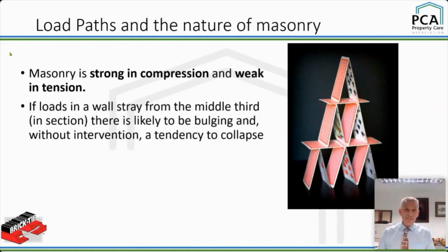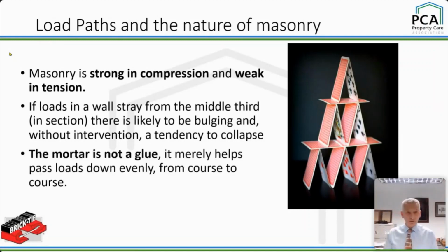That's what we mean. If loads stray from the middle third in section down a wall, then there's likely to be a bulge. Because we want the load path to go down the middle, right? There's likely to be a bulge. If we ignore that bulge, then those collapses that we've seen are going to happen, all right? So bulges are important.